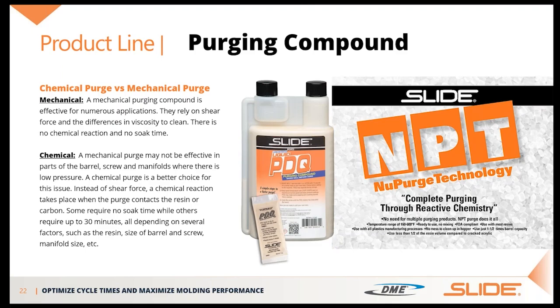Ours is chemical. So the main difference is, mechanical purge uses physical scrubbing and friction in order to clean. A chemical purge, of course, activates, and it has basically soaping agents that will attack resin and carbon buildup in the screw and barrel.